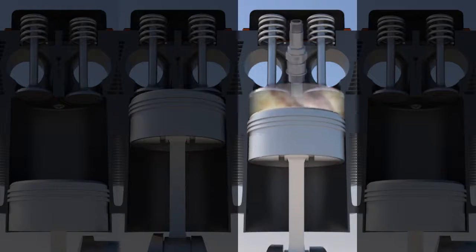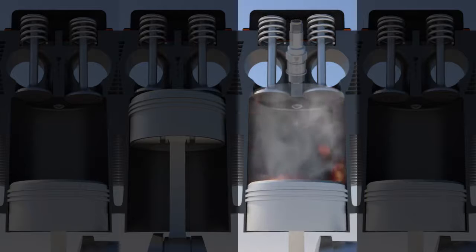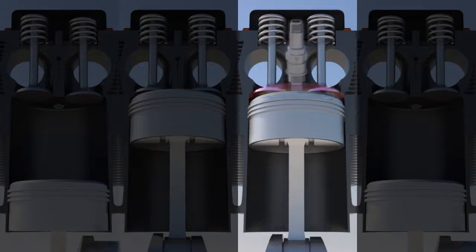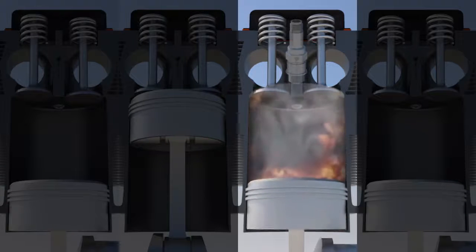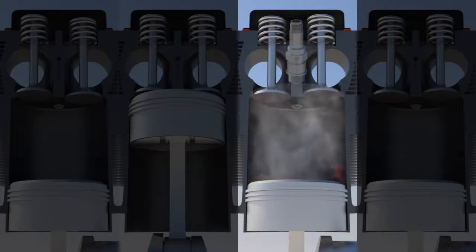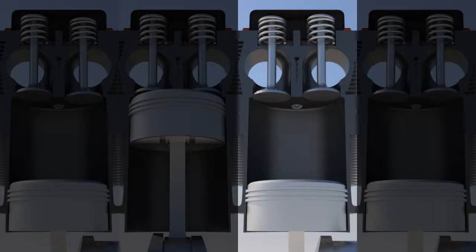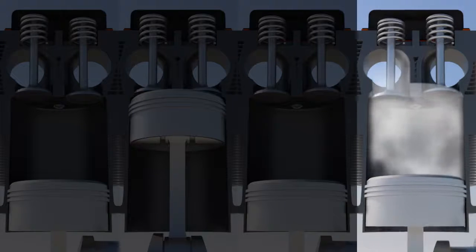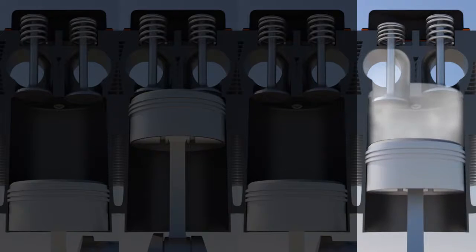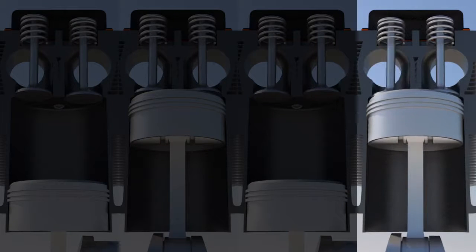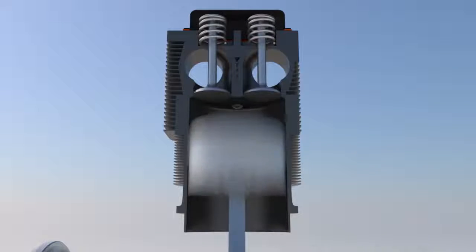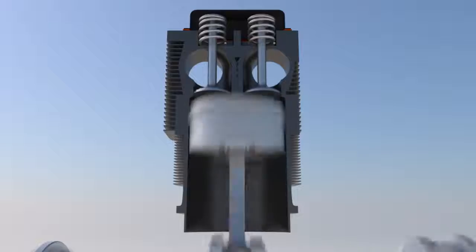Two spark plugs at the head of the cylinder each let off a spark, which ignites the fuel mixture and makes it combust. This controlled explosion pushes the piston back inward towards the base of the cylinder, which in turn rotates the crankshaft, and therefore the propeller. Finally, we reach the last stroke, exhaust. During this phase, the exhaust valve opens, and the piston moves back towards the cylinder head, pushing out the combusted gases, commonly called exhaust. Then the process starts all over again, repeating thousands of times every minute.